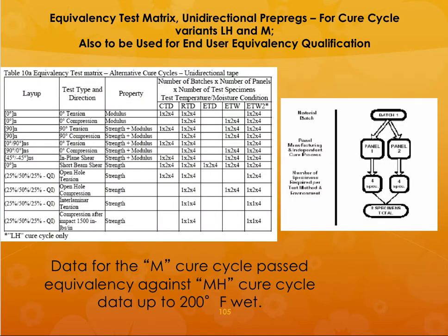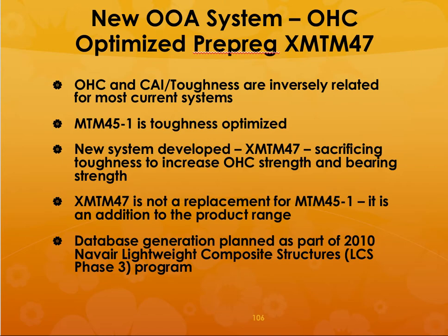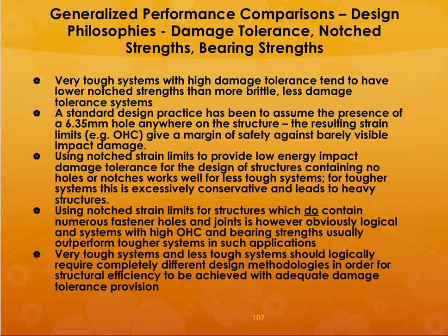If you have to do equivalency of this data at your location, you have to test at least 8 samples under each condition. Especially under certain circumstances, like if you need damage tolerance, you need to make sure that you accept more conservative values than the averages that you are getting.